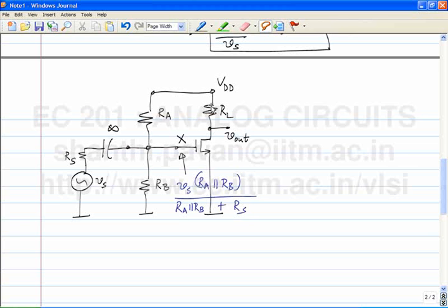There are many loads. For example, the loudspeaker is one such, where if you have DC current through the loudspeaker, it will saturate the magnetic core, and bad things can happen. So it is usually not a good practice to have DC current through some loads. Okay. So in other words, we need to figure out how to avoid DC current flowing through the load. Any suggestions on what I can do?